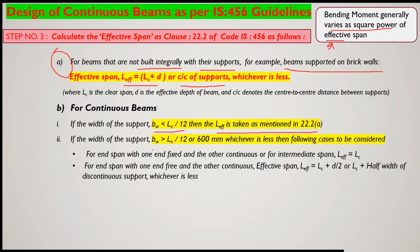Now, if the width of the support is more than this or 600 mm, whichever is less, so first you calculate LC by 12, whatever its value, then compare it with 600 mm and take the lesser value. Now, if the width of the support is more than this lesser value, then you have to consider these two cases. For end span with one end fixed and the other end continuous, or for an intermediate span. So here we have two conditions. First is end span with one end fixed and the other end continuous.